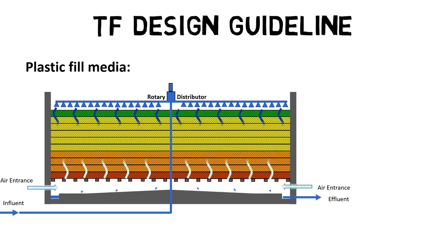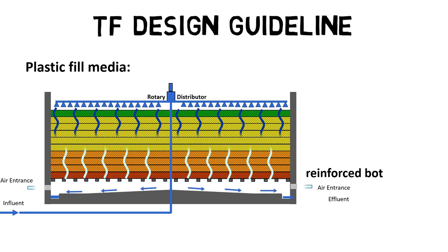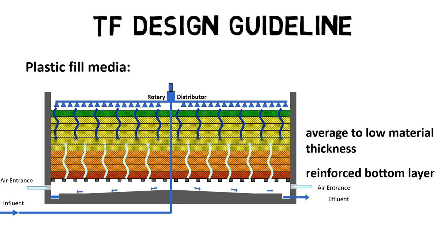The material thickness of plastic fill media foils can be varied depending on the structural loading requirements. Therefore, for a long lifetime, 30 years, the bottom layer should be reinforced, followed by average to low material thickness fill media layers, and finished with a high material thickness, reinforced top layer.